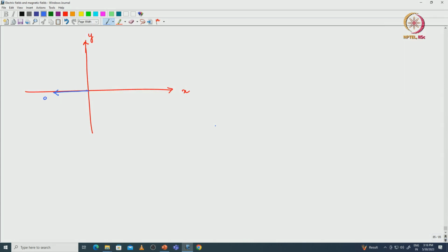So, this is at 0, and then at 45 we have seen at this particular point, and then at 90 degrees the resultant flux vector is in this position, and at 135 degrees here, and then at 180 degrees, and then at 225, then 270, 325 degrees, and then again at 360 degrees is equivalent to 0 degrees.